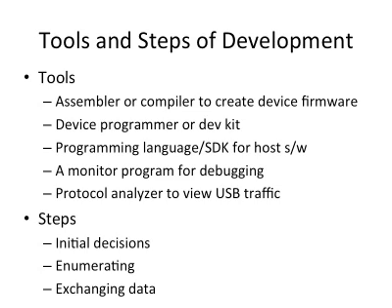There are certain steps you need to take. You want to do some initial research to make your initial decisions on what kind of controller you need to use and what kind of programming environment you want to use. And you want to implement some of the key communication. For example, enumerating, which essentially refers to how you want your device to be recognized. And the last step will be the actual exchanging of data between your host and device.